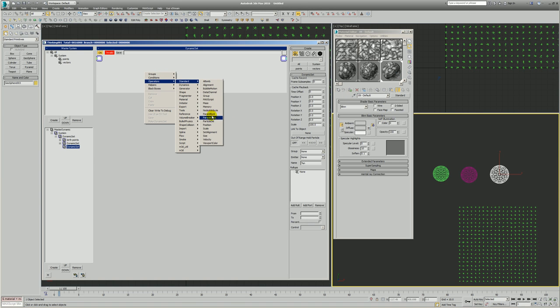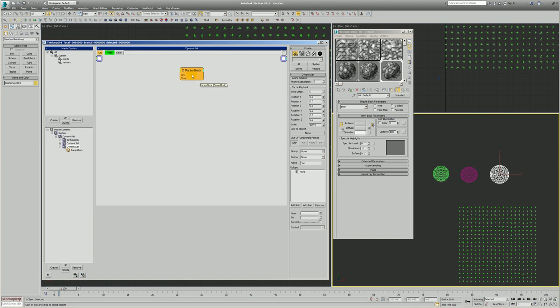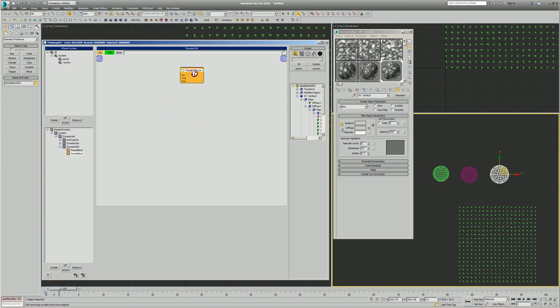And again, thinkingParticles has given us a very useful tool called paramblock, which we can use to access an object in the scene and access anything connected to it, basically. And in this case, we're going to use the smoke map, and let's control, for instance, the size. And we'll duplicate these.